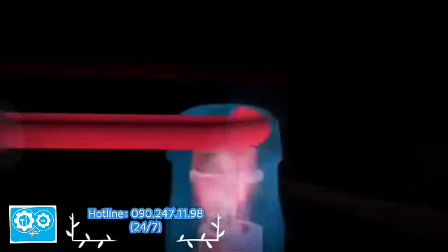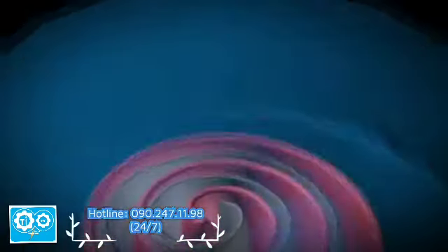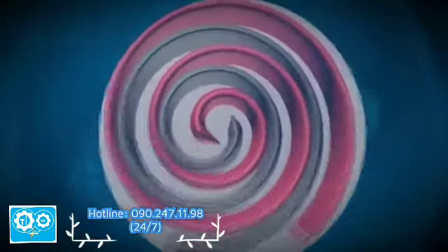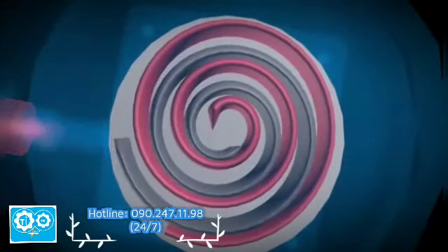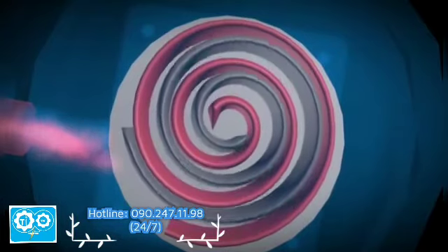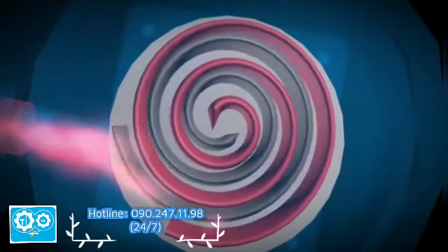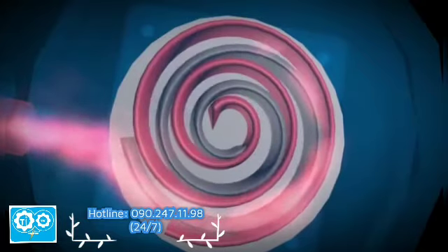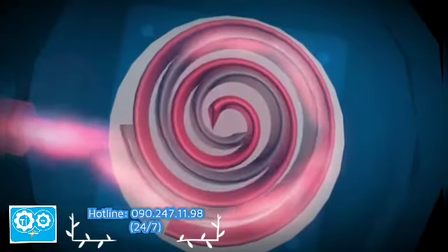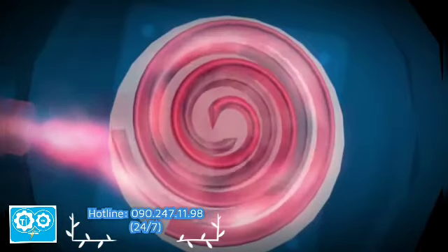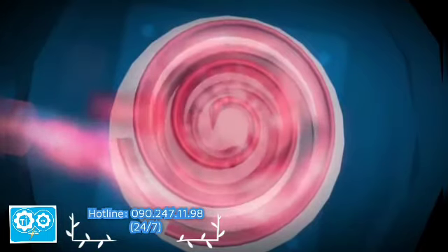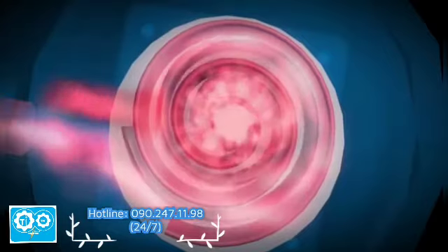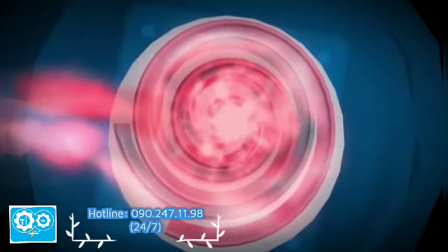The type of compressor used is the scroll hermetic type. The scroll compressor works as follows: gas at low pressure and temperature enters the suction line and goes into the compressor. The low pressure and temperature gas is pressurized by the scroll compressor to high pressure and temperature gas. The high pressure and temperature gas is then passed through the discharge line and goes into the condenser.